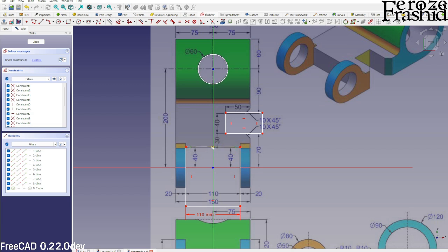But if I said, so let's delete that, if I said symmetric by any point, for example, say origin, this will actually fix it at that point. If this was horizontal, this line would be immobile, I cannot move it anymore. It would be symmetric on the lateral side, and up and down it will be fixed too.